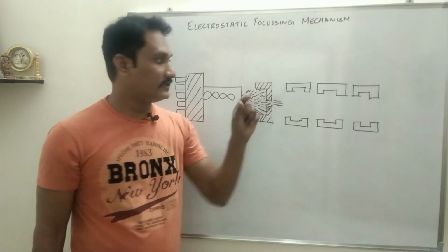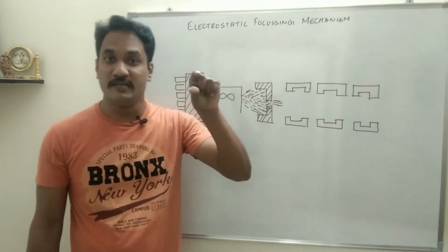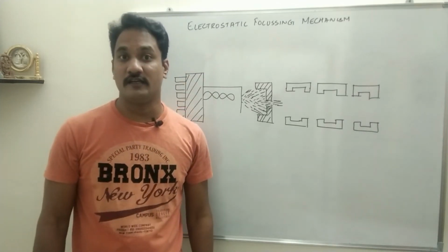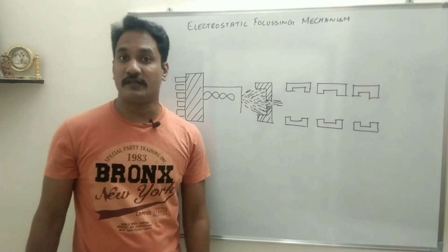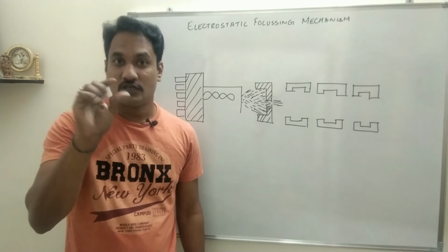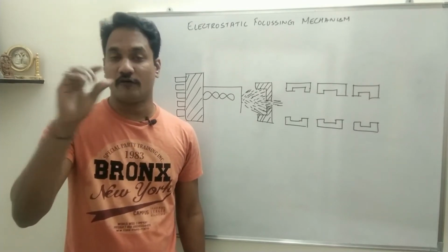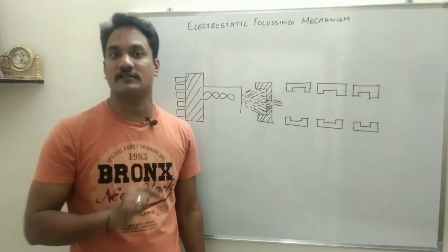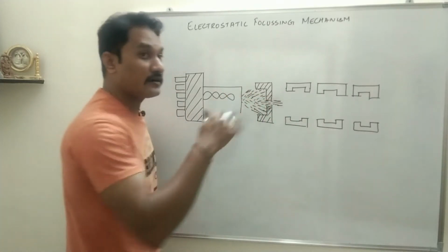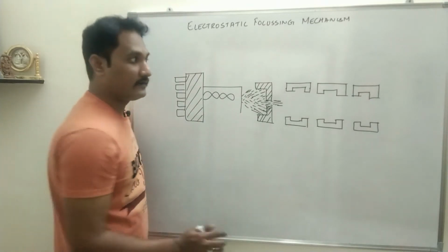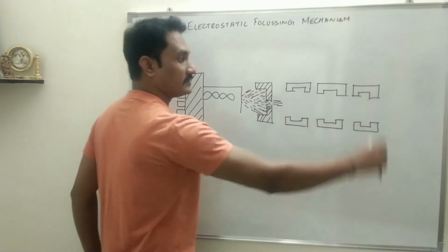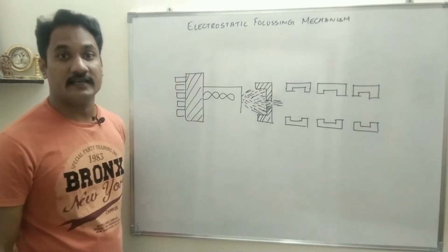Focusing means, the electrons moving out of the control grid are a beam of electrons, and of course they are going to diverge when they enter the pre-accelerating anode. What you want on the screen is a small, sharp dot. So you need to focus this entire beam of electrons to a sharp dot, and that is the second use of these three anodes. In the block diagram of CRT, I said that the focusing anode, the center one, is connected to a less positive potential as compared to the pre-accelerating and accelerating anodes.